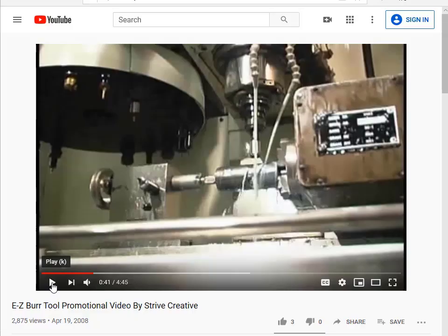So you make the burr, and really the burr is a type of defect, and we've talked about that in our quality class. For those of you who have been through that class and heard me or the manufacturing professor talk about this, a burr is really a defect. It's something that you make that you don't want, and it's better if you don't make it in the first place. But occasionally, you cannot get around it, and this is a way to eliminate it after the fact.